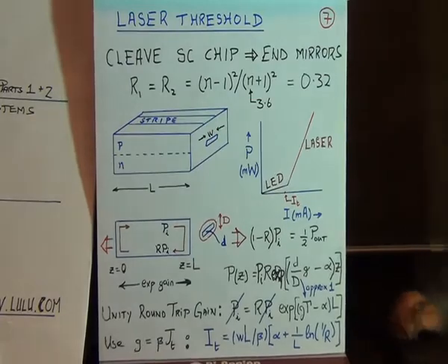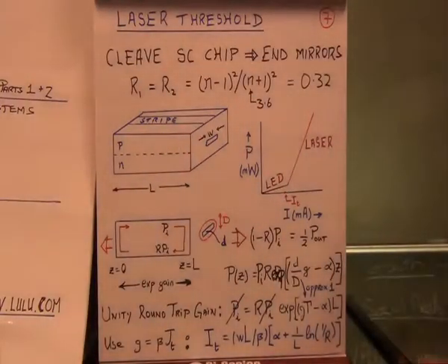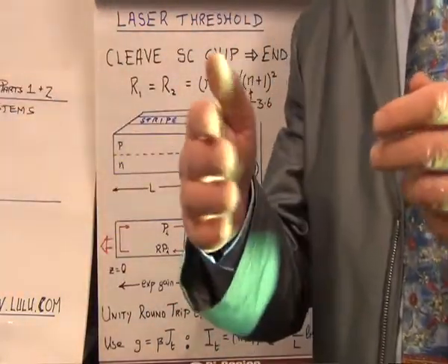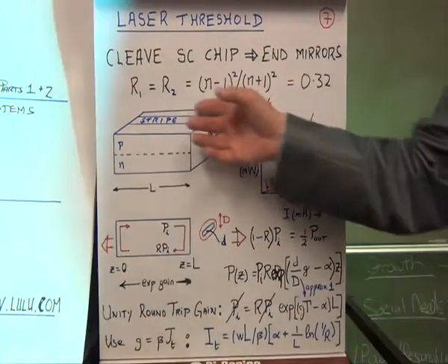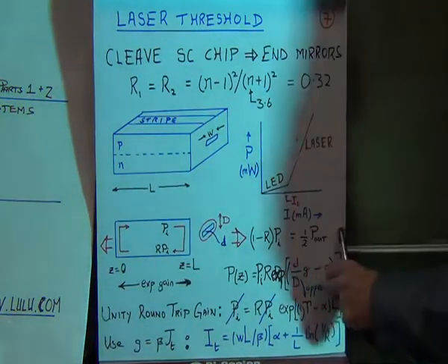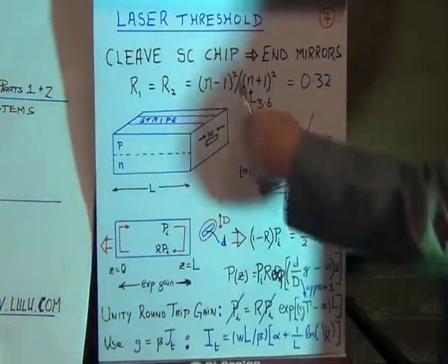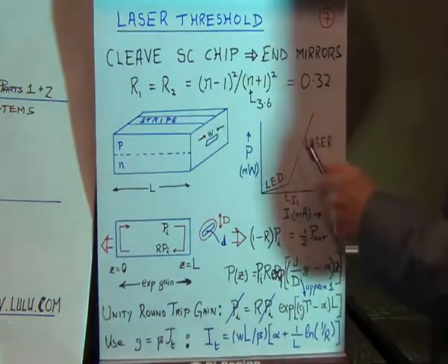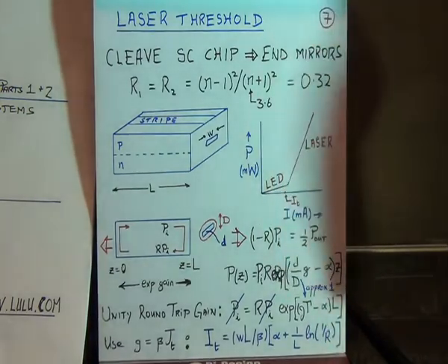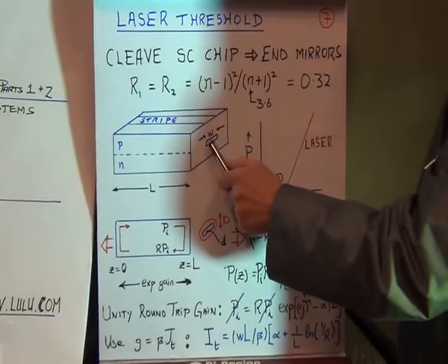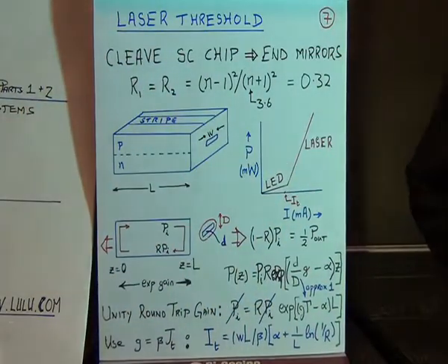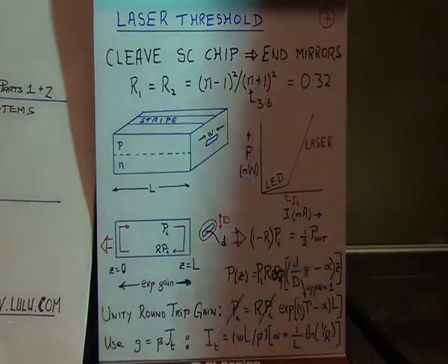That's Fresnel's equation. It's the same as the equation you have in your electrical circuit theory, where you have an impedance Z1 and you arrive at an impedance Z2 and you get a transmission and a reflection. Same form of expression. If you think back to the Z1, Z2 equations, they look just like that. Now, it turns out it's just the kind of number we want. Do it yourselves with your calculator, you see it's about 32%. So over 60% of the light is emitted at this end, and it's identical at the other end. So our laser has two outputs.